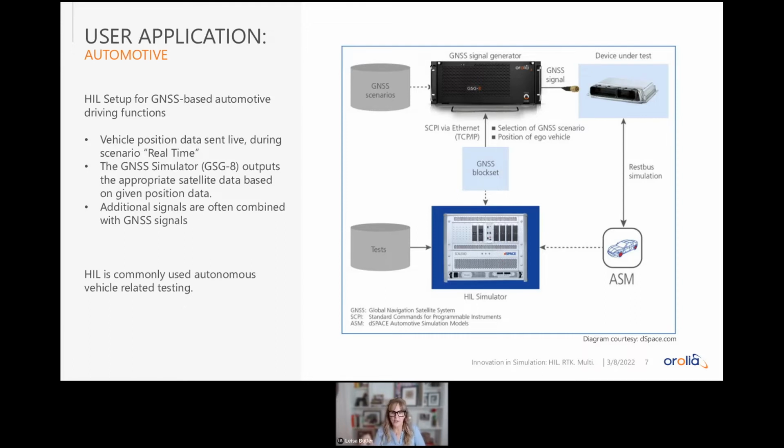Now, you can also run scenarios and do other things from a HIL simulator, just depending on your setup. But the HIL simulator is typically a different device driving the GNSS simulator to take action. And again, as we mentioned before, you'll often have other signals included. So whether it be CAN bus or sensors or radar, LiDAR, whatever it is, all done in real time.